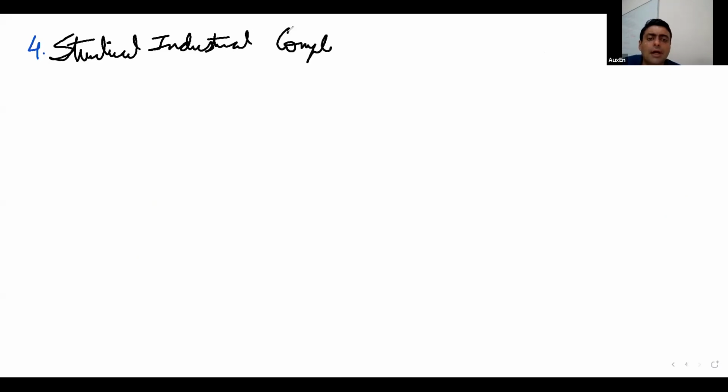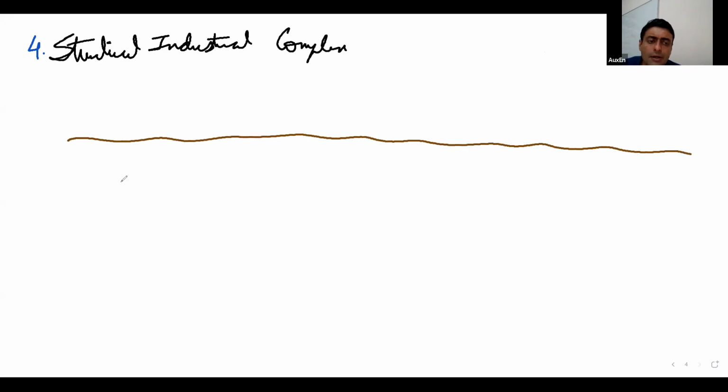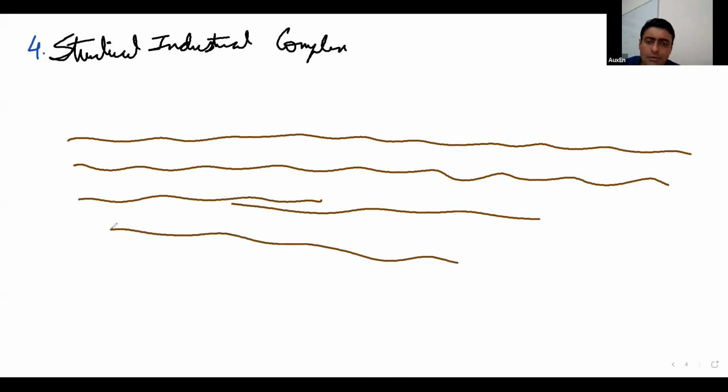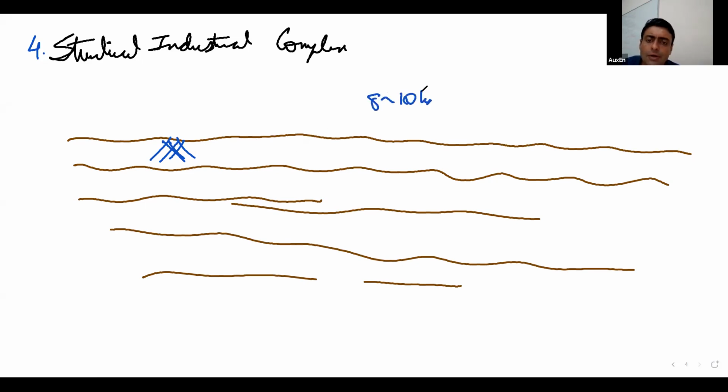Now in Bengal, or in the entire northern plains, there is a thick alluvial soil bed, because of millions of years of alluvial soil carried by the rivers, Ganga, Yamuna, countless rivers. Those alluvial beds do not give you proper bearing capacities. They will give you only around 8 to 10 kilonewton per square meter, which is very low. So we had to make a large industrial complex.